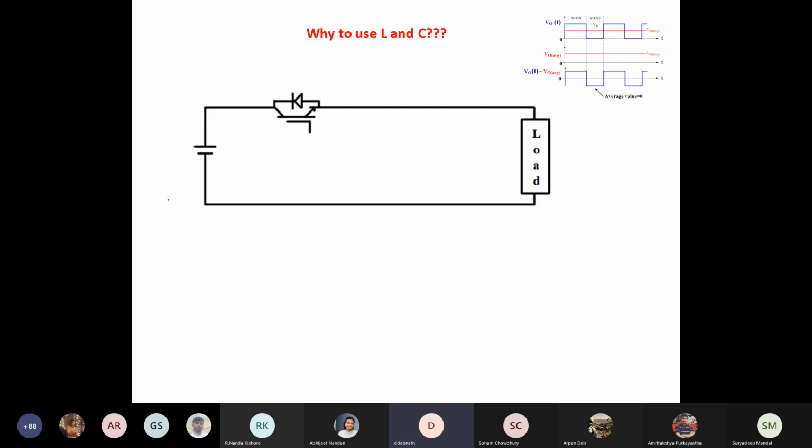So now, let me quickly tell you about this step. How can you think and how can you actually solve these problems? So most of you will agree that in rectifier, you must have studied, right? We use a capacitor filter parallel to the load. Do you agree? Remember, half bridge rectifier, full bridge rectifier, you used to add a capacitor, right? So that you can make the output voltage flat. Otherwise, output of full bridge rectifier used to look something like this. But then you used to take capacitor.